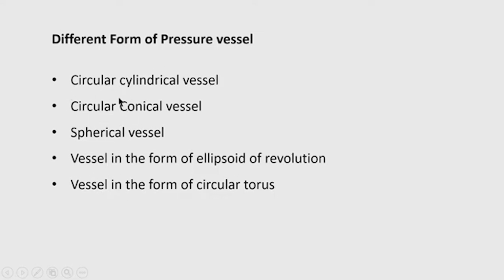One by one we will discuss them and see how the theory is developed. The theory is our membrane analysis for axisymmetrical loading condition, and our target is to find the meridional stress n phi and circumferential stress n theta for design purposes.